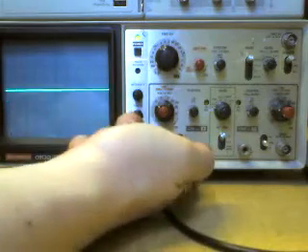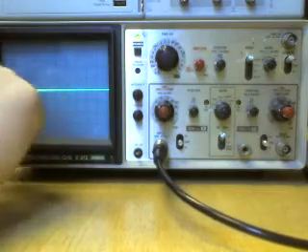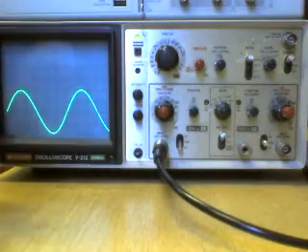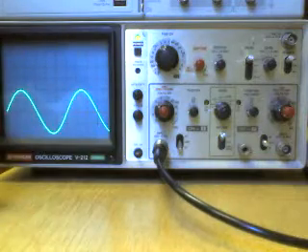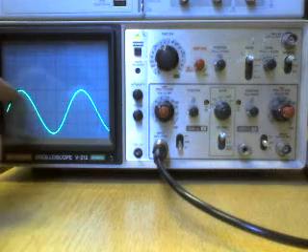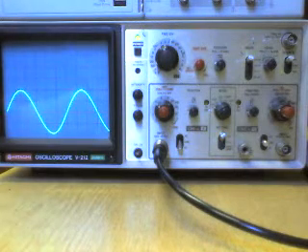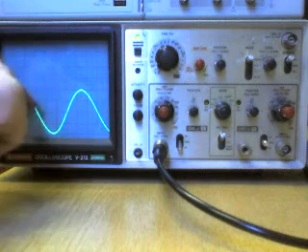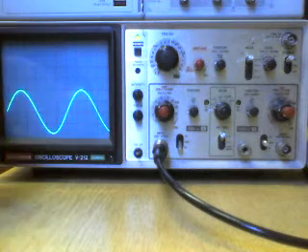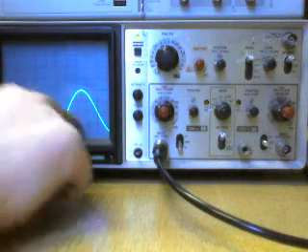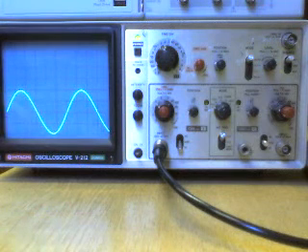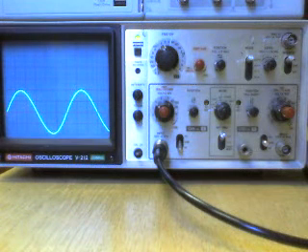And that's the beauty of this coupling thing. Because we set it originally to ground, we know where ground is. When you switch it to DC, you know that it's gone negative because it's on the bottom half of the screen. Simple. But the peak-to-peak value is still the same, still 2 volts peak to peak, with a -1 volt offset. Done. Period hasn't changed, voltage doesn't change, time stays the same. And that is how you measure on an analog oscilloscope.